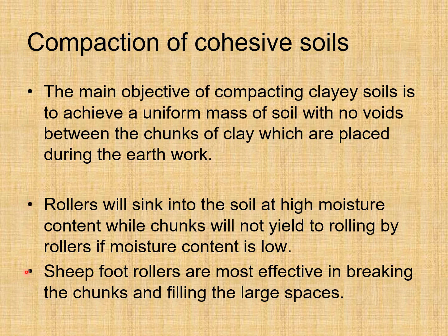Sheep foot rollers are most effective in breaking the chunks and filling the large spaces. I'm sure you are familiar with the sheep foot rollers. In the case of sheep foot roller, we have projections upon the drum of the roller.